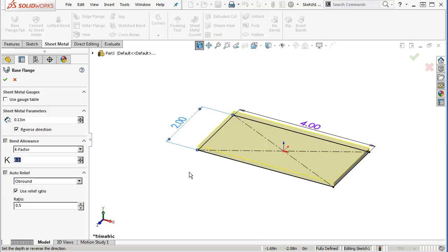What happens when we take a piece of 60 by 120, 10 gauge, and do whatever laser pattern or plasma pattern, and then take it over and start bending it up over feet, not inches? Then that growth becomes a lot more apparent. And as you get into thicker materials, definitely so. All right, so we're going to see 4x2. We'll go through the process and see what it comes up with for actual measurements. At 2 decimal places, I wouldn't expect to see a lot of variation.